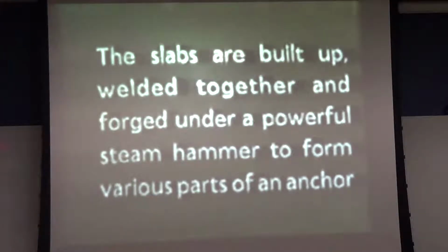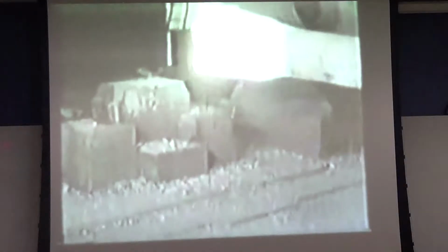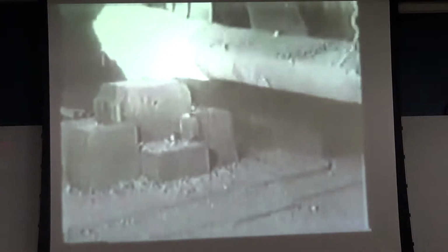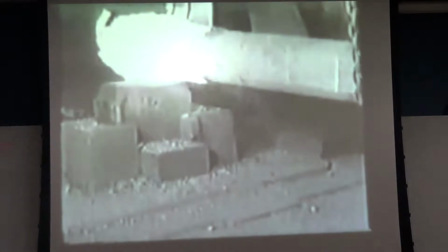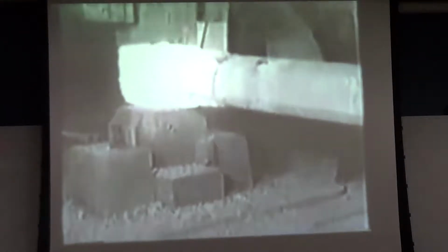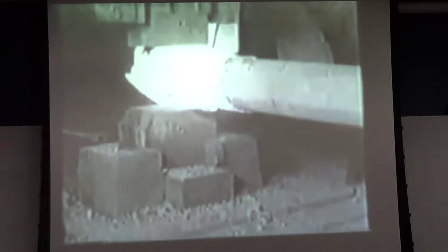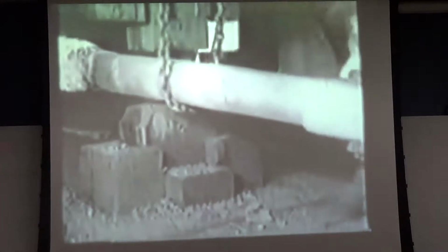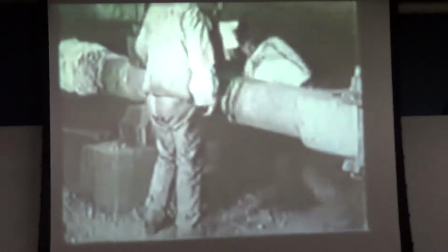And so we just saw them pull a chunk out of that, and that's what was dripping, was the iron silicate. And then they would pound on it to get that into a uniform block, and that uniform block could be pounded against another block, and so on, and you could build up a large item from a whole bunch of relatively small starting pieces. Typically, those starting blocks would be roughly 500 pounds.